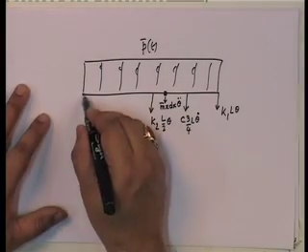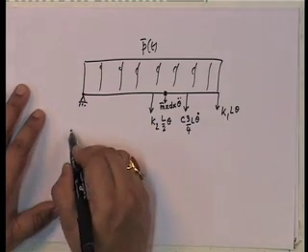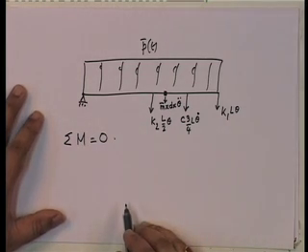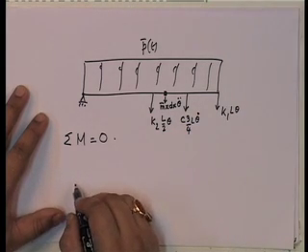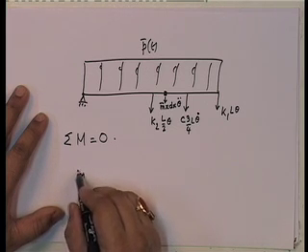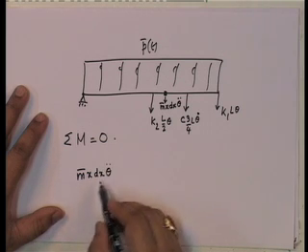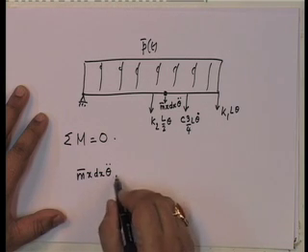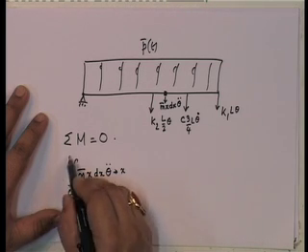So, if I take moments again, since this is the point about which I know, moment equal to 0, then what do I get? Now I can put these down. I get m bar x dx theta double dot, the infinitesimal force multiplied by x, and this integrated over the whole length.